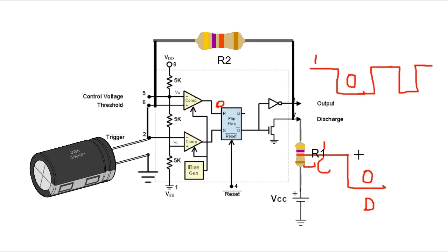So we can exceed this duty cycle to 80%, 70%, and the only thing that you need to remember is that the IC555 as an astable multivibrator, its duty cycle cannot go less than 55%. So we need to modify this in order to generate a PWM pulse.